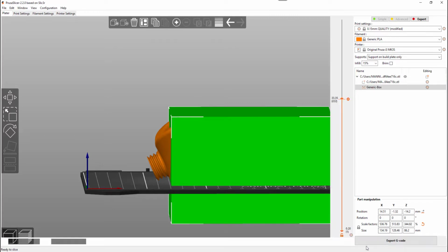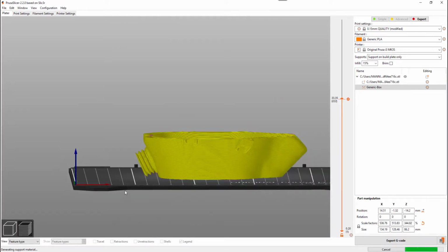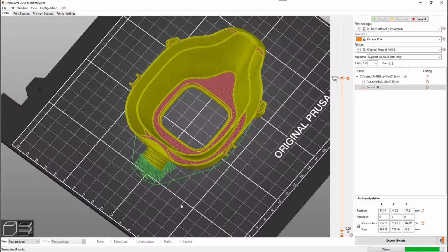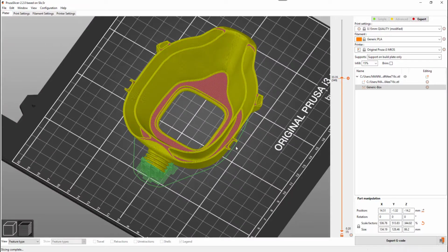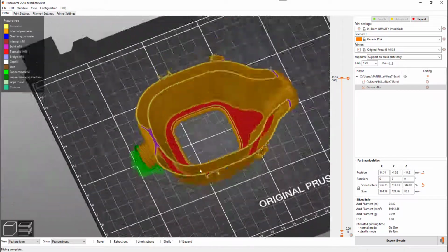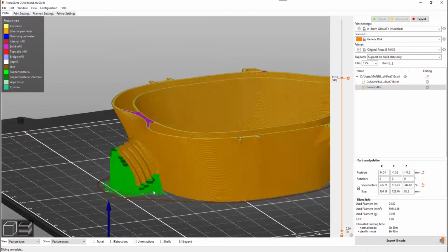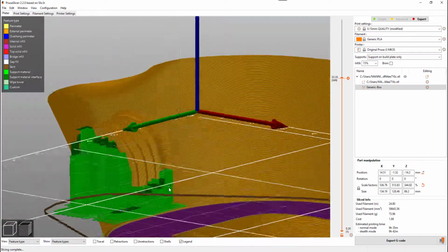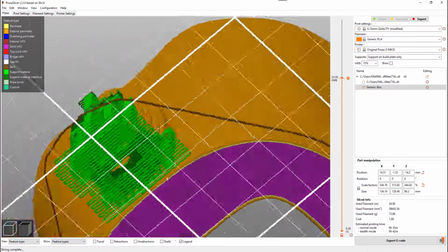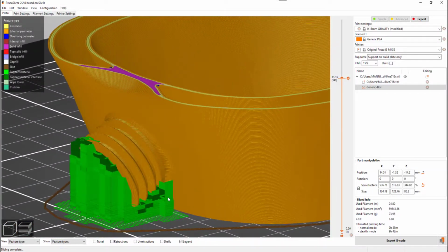So build plate only, slice again, and it'll run through that. And this time you'll see we don't have any supports around these bridging locations. So that's good. It's good to support the nozzle here. You could change the orientation, but I fear the supports would be bad. The test ran these supports really well. You could try it without, but I wouldn't recommend it.